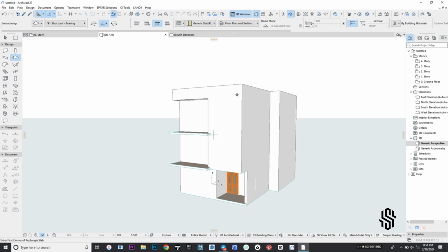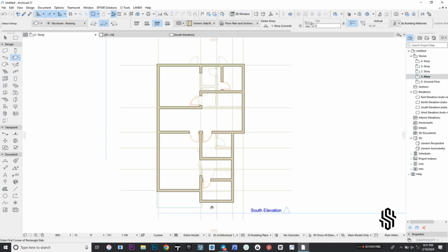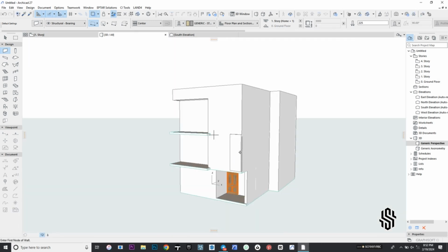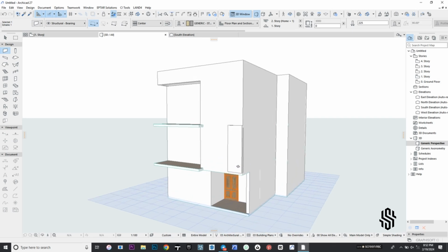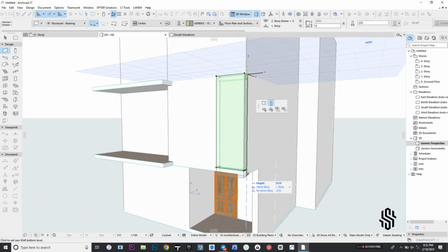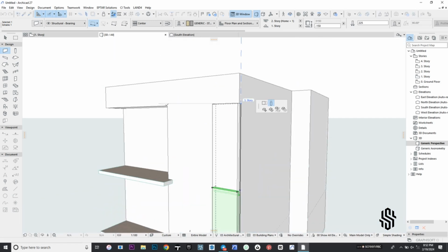Next, we want a shape, an L shape from the top to the bottom. So what we will do is create an extra wall in front. This can be done on site as plaster effect or any other thing, but we're going to make use of 1 meter since our top has 1 meter, exactly like this. I'm selecting it and I'll extend the bottom to where the slab begins, and I'll extend the top to where the parapet begins.